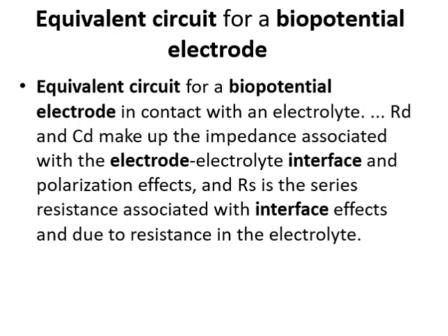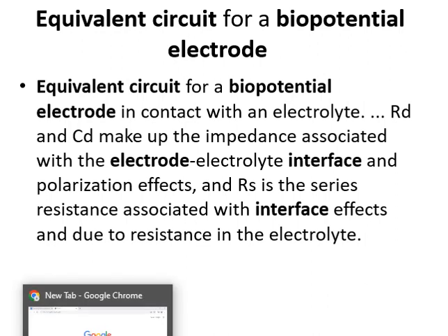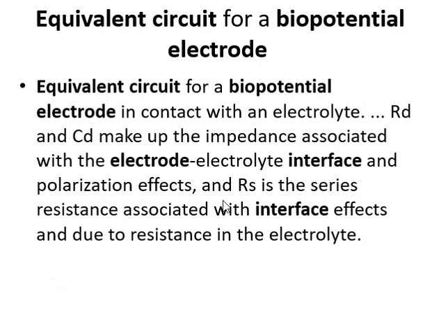Biopotential electrodes should be able to conduct small current across the interface between the body and the electrode measuring circuits. Oxidation is dominant when current flows from the electrode to the electrolyte, and reduction dominates when current flow is the opposite. These are the properties of biopotential electrodes. Biopotential electrodes are acquired with the help of specialized electrodes that interface to the organ or the body and transduce low noise, artifact free signals, which are the characteristics of biopotentials.